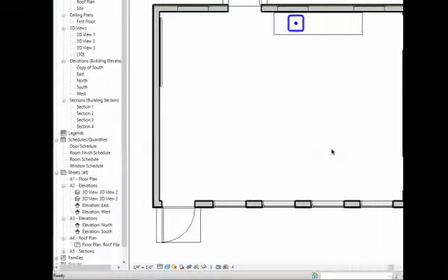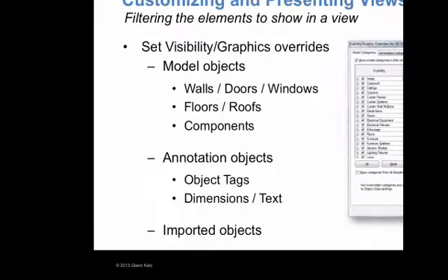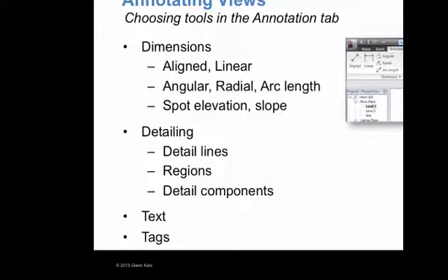Okay, filtering is where we often start with changing things in the different views. But after we filter to show the things we want, we often put some annotations in there to call out things that aren't obvious by default. Let me show you what I mean. This is the whole notion of visibility graphics, going through and turning things on and off or overriding the appearance. Okay, let's talk about annotations and some of the things that are available there.